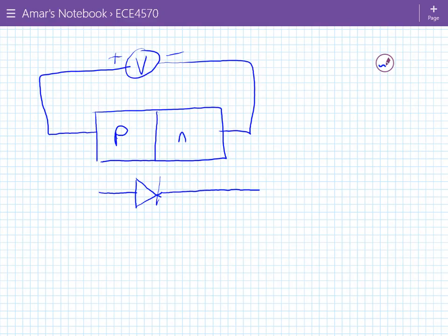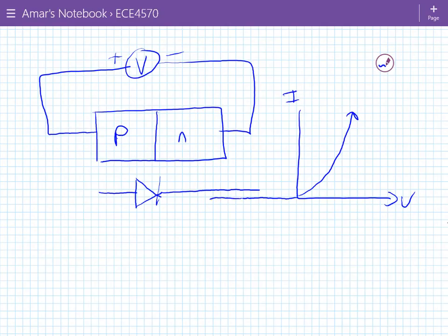In your Electronics 1 course, you've talked about what the model is for a diode. You know that it has an exponential IV characteristic. It only conducts current in one direction. So in the negative end, the current goes something like this. And when you get to very large reverse biases, there's another phenomenon called reverse breakdown that causes the current to increase rapidly once you get to a large enough reverse voltage. How many of you remember these curves from Electronics 1? Okay, about half of you.